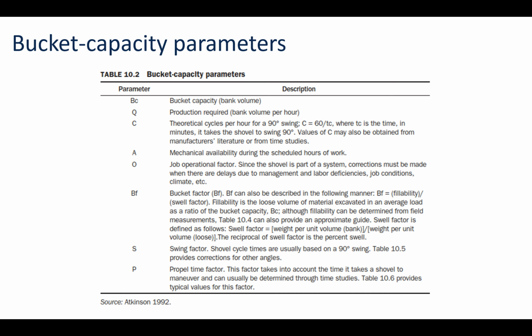So when you would do an overburden calculation and you calculate that volume, either using software like Carlson software or something like that, or using analytical techniques, just math to solve it, either way, we're calculating this in bank volume.